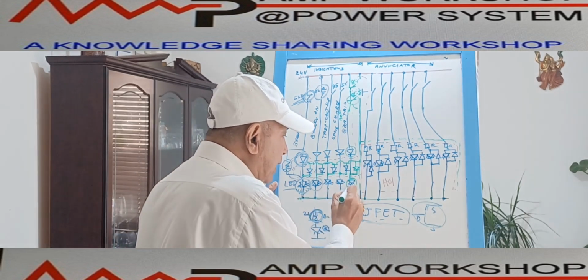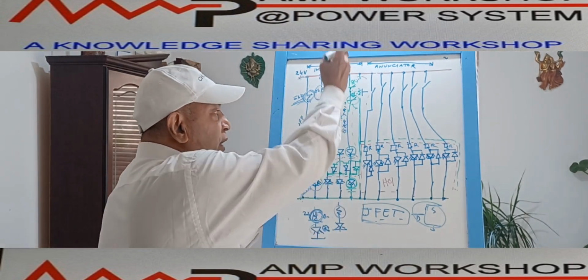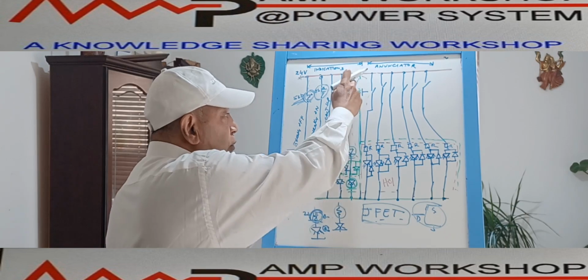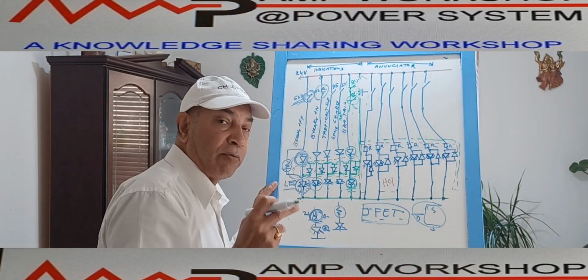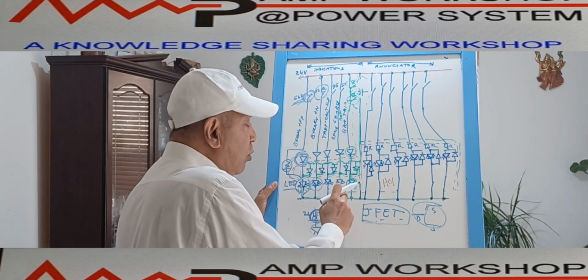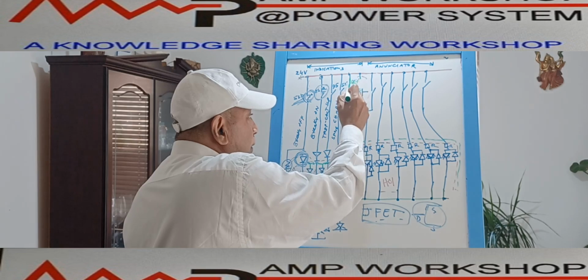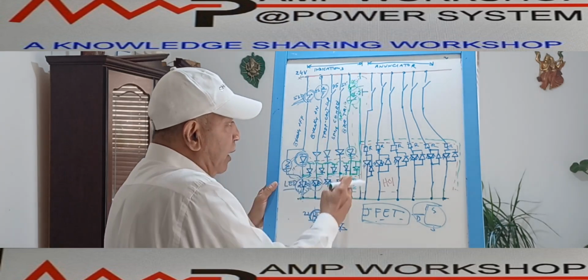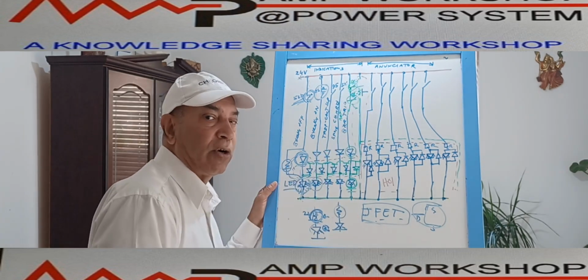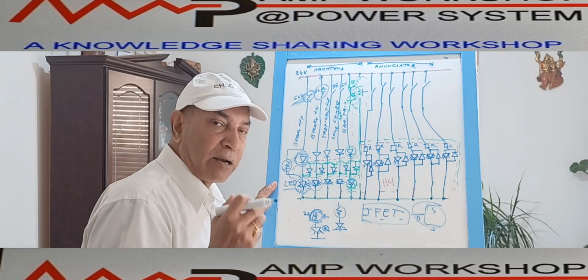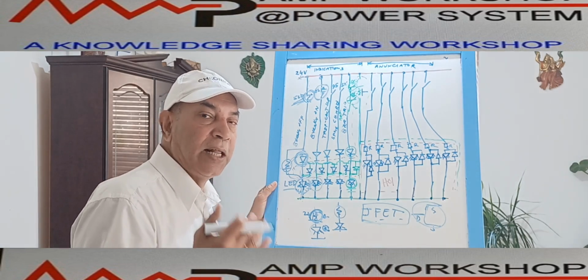But as long as the LED is on, the circuit is in healthy condition, because only when both lockout relays have not operated will the LED be on. If either lockout relay operates, its corresponding contact will open and the circuit will be discontinued. So this LED indicates that the circuit breaker or the electrical circuit is operating in healthy condition.